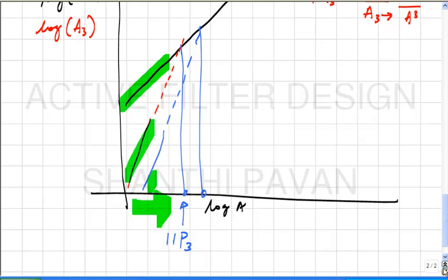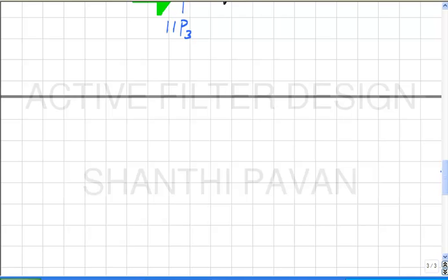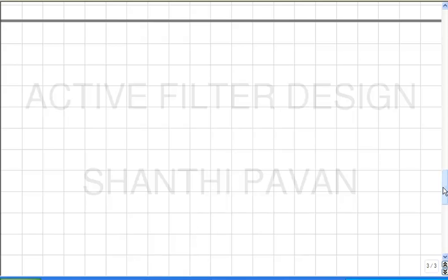Then the last minor point I want to mention. This has got to do with your homework and nothing else. So in class we saw all these fixed GM bias circuits, which were based on putting the delta V and then measuring I and then using a negative feedback loop to fix the transconductance. In the assignments we saw circuits of this kind.